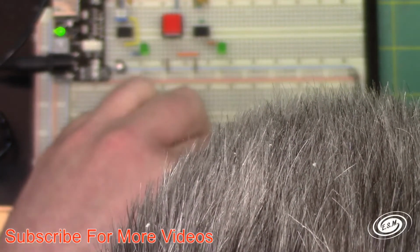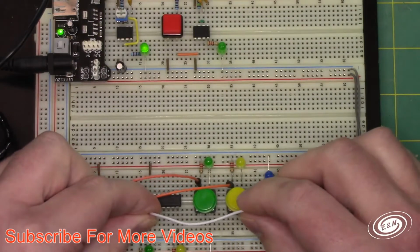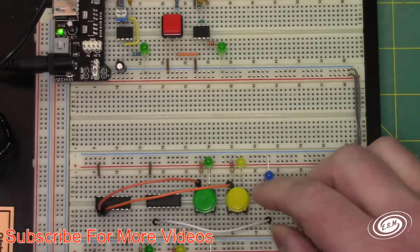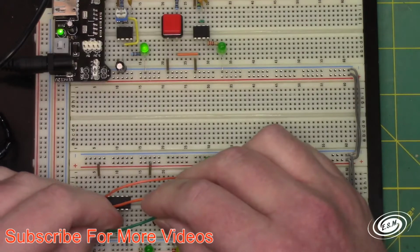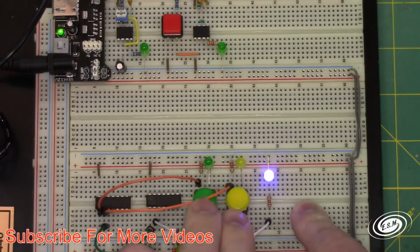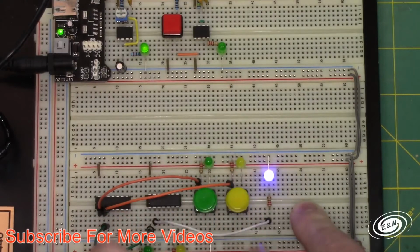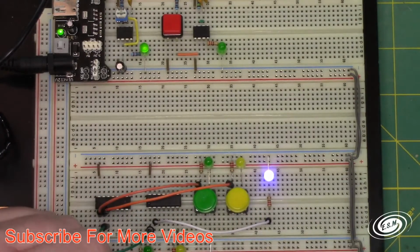Plug that one to that one. And then I'm going to take my output, which is here, of my inverter, and throw the output of the AND gate into the inverter, and now I have an inverted signal, and if I press them both it goes off. I press 1. So I made a NAND gate with the AND gate and an inverter.